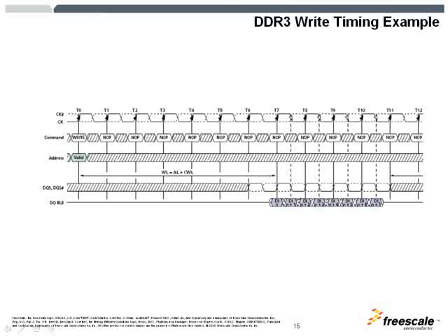Similarly, here is a DDR3 timing diagram, and here again, as indicated before, the bursts for DDR3 are only 8 beats, and there are no 4-beat selections. We'll discuss this further, but just keep in mind that DDR3 is always 8-beat bursts, and so as you can see, there are 8 beats of data on the bottom.